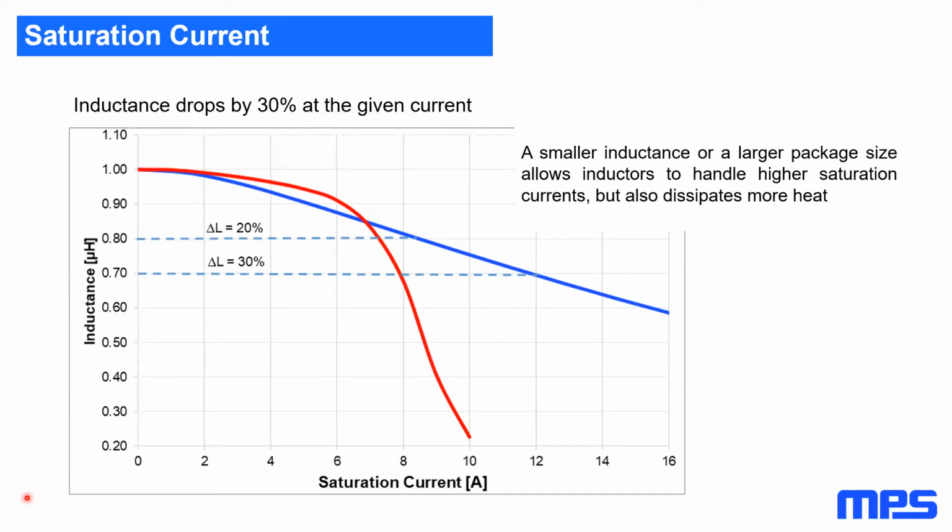Number 3 is the Mpl-A-L. Unlike the other series, this series is built up with a flat wire winding. We've learned today the use of flat wire can lower the DCR and thus reduce the DC losses. This makes the Mpl-A-L series highly efficient and perfect for high performance applications.